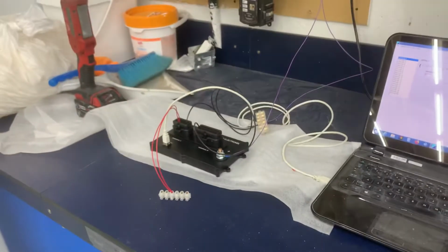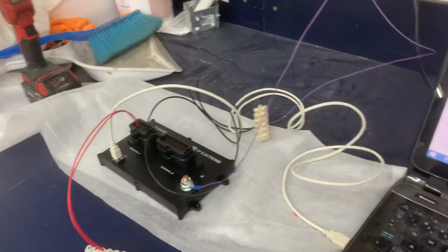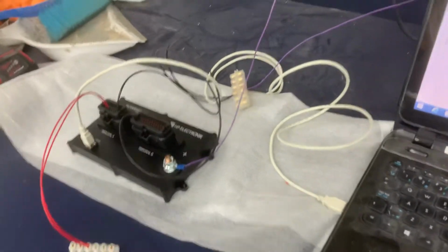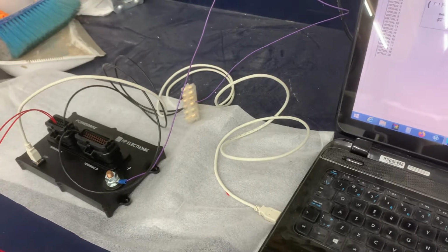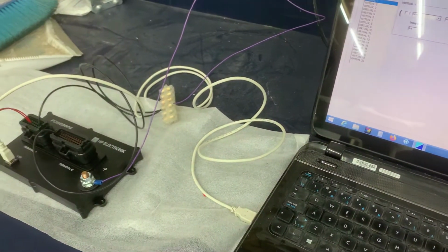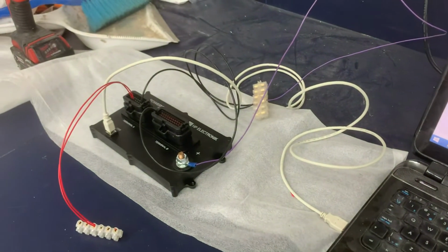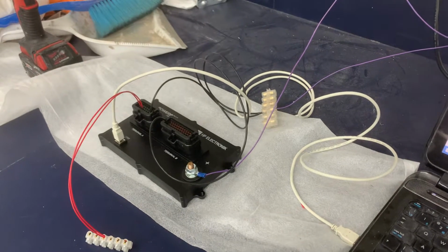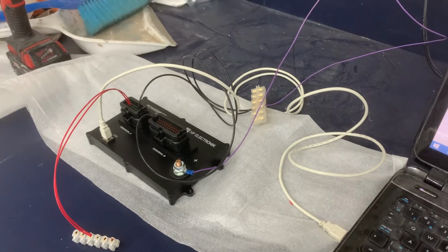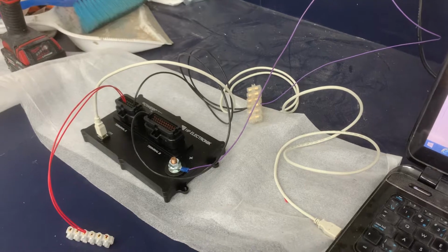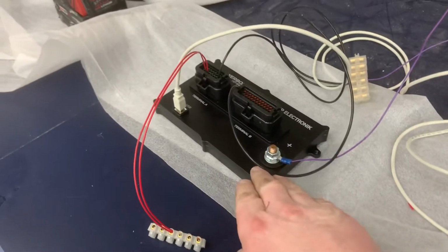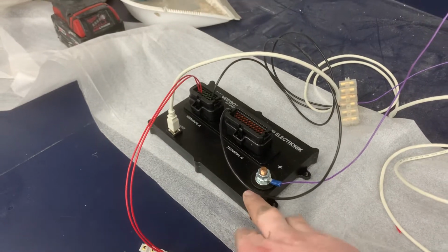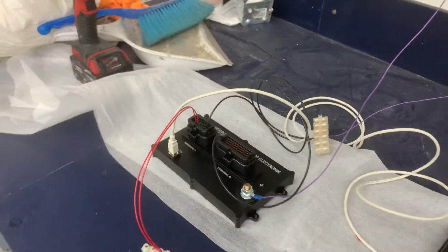Excellent. Since then, I've realized that ECU Masters do a CANBus protocol style TPMS system with the 4 wheel speeds, and the 4 tire pressures and temperatures, which is good. So basically we'll buy that. The CAN information will go to the ECU via that little box.